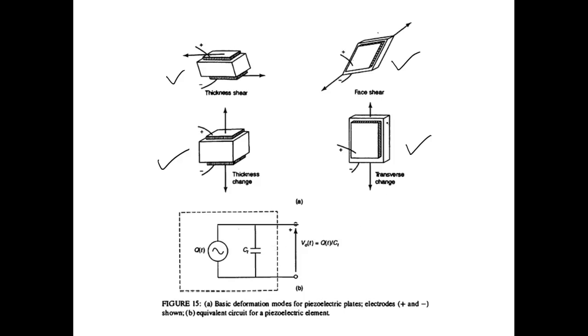So obviously we can put these materials under these loads, and we can do two things. One is we compress them and get a voltage. The other is the reverse piezoelectric effect. They are reversible: we apply voltage and it causes deformation of the piezoelectric material. So to have very high frequency deformations, compression and expansion, to generate something called ultrasonic waves, we also use these materials.